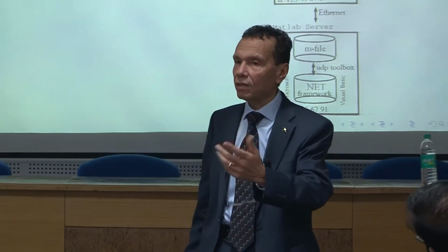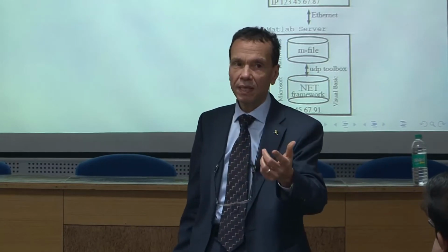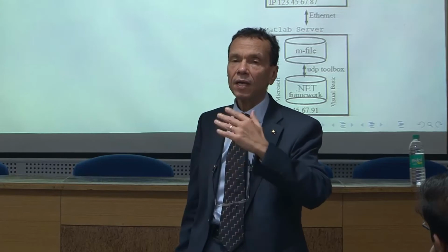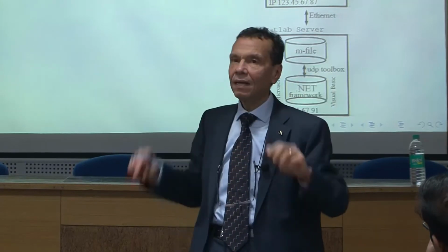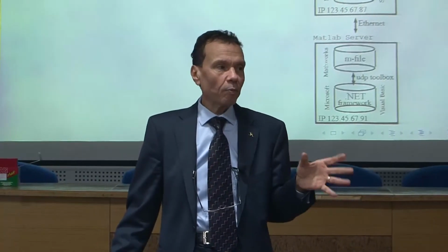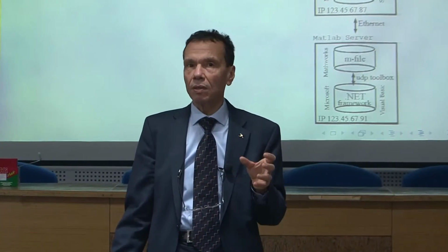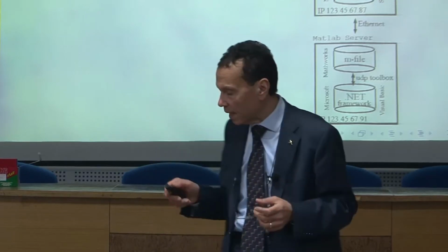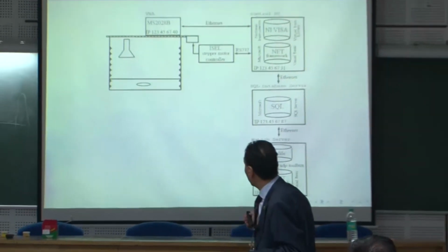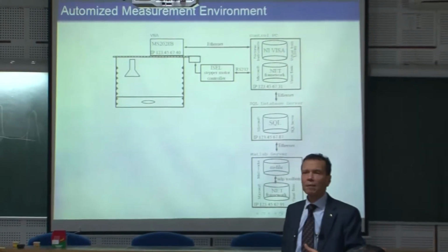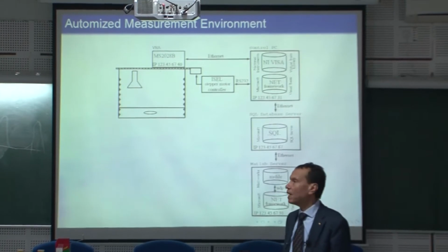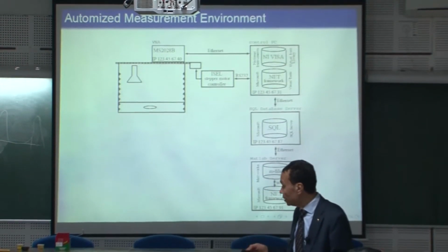If you don't have snapshot information, which you can sample just once, you can apply this in order to have higher sampling, or equivalent sampling, provided that you have a really repetitive phenomenon. And in measurement, it is possible to apply. Okay, so whether you use real-time sampling or equivalent sampling, you now have your data in digital form.